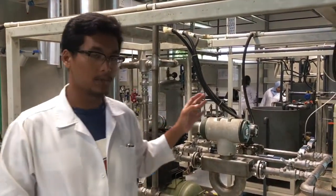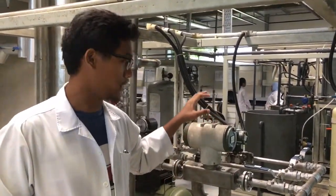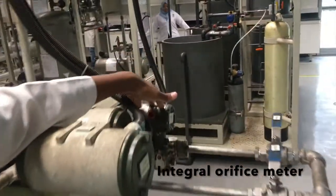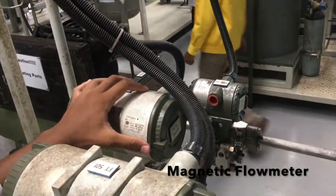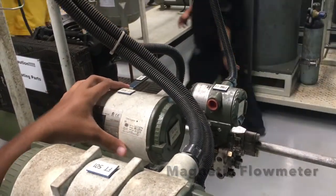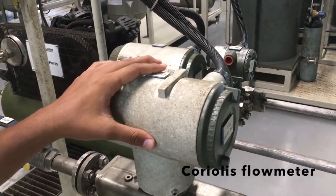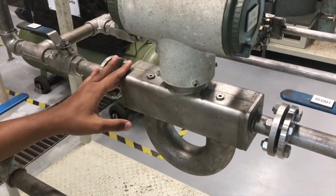Meter measurement. The objective of the experiment is to compare the accuracy between three types of flow meter. The first flow meter is this one. It's using an Orifice, and this is the electromagnetic flow meter using a magnetic field. And this is a Coriolis flow meter, which uses Coriolis effect to measure the mass flow rate.